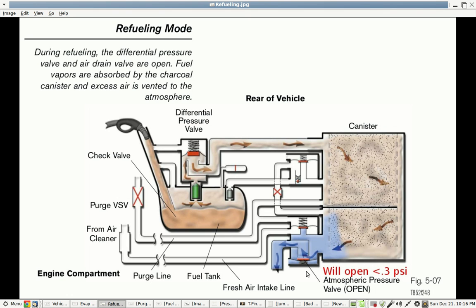the air would try to come back up the fill tube where you're putting the gas in, and then your nozzle's always trying to click off. So that's where you're trying to put gas in and you put like 30 cents in and it clicks off, and that's very frustrating. Well, what's happening is your venting system is not allowing it to purge out. Something has malfunctioned with that.